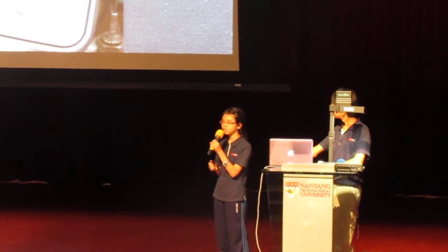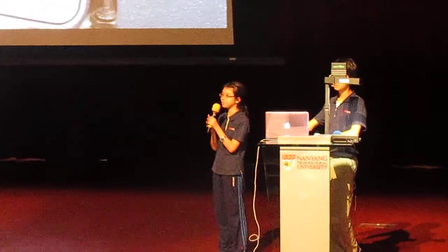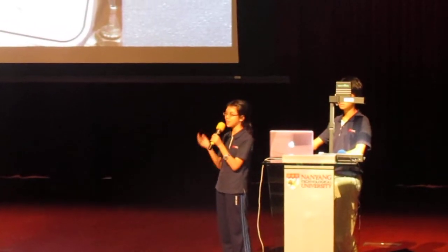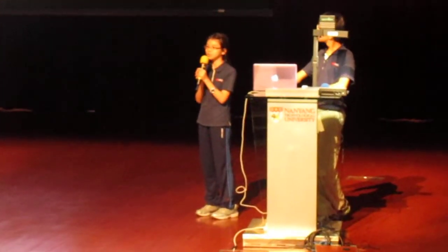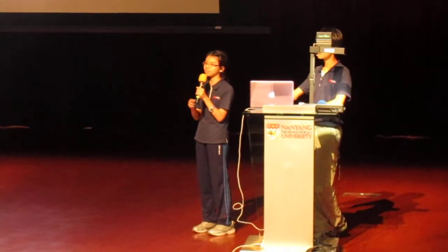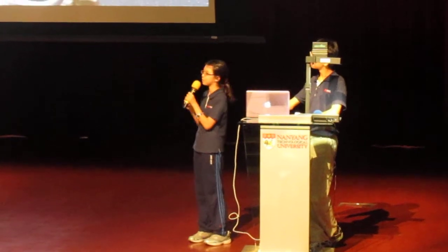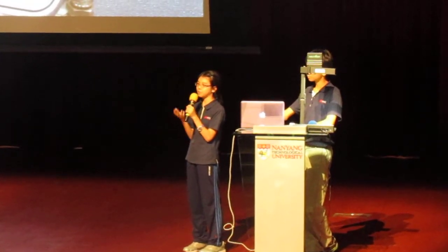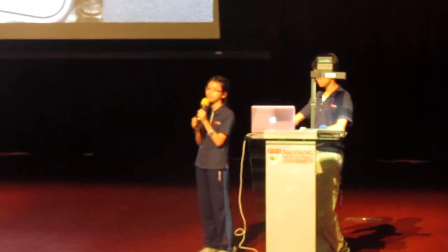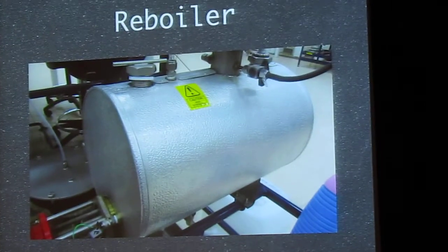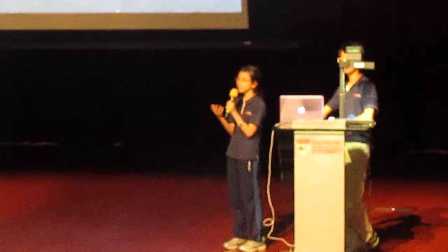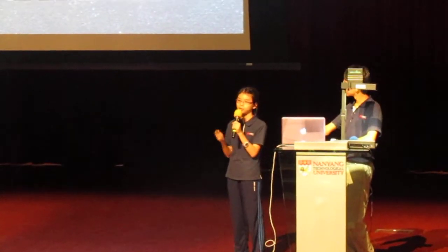This is the top product receiver. The top product receiver is the container to hold what you have distilled in the end. In our experiment, we need to distill the mixture of ethanol, which is the alcohol, and water. In this top product receiver, the liquid that you will find has a richer content of ethanol. The reboiler is another storage for the feed, but it has a heater behind it to provide heat.